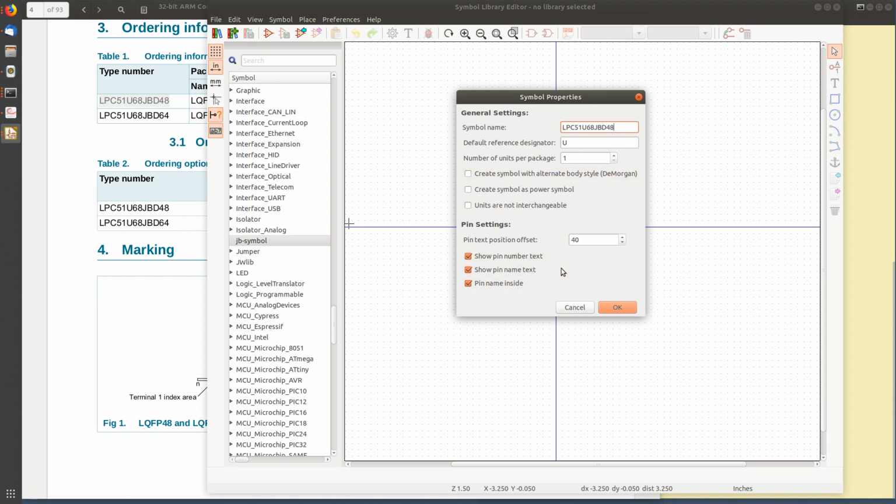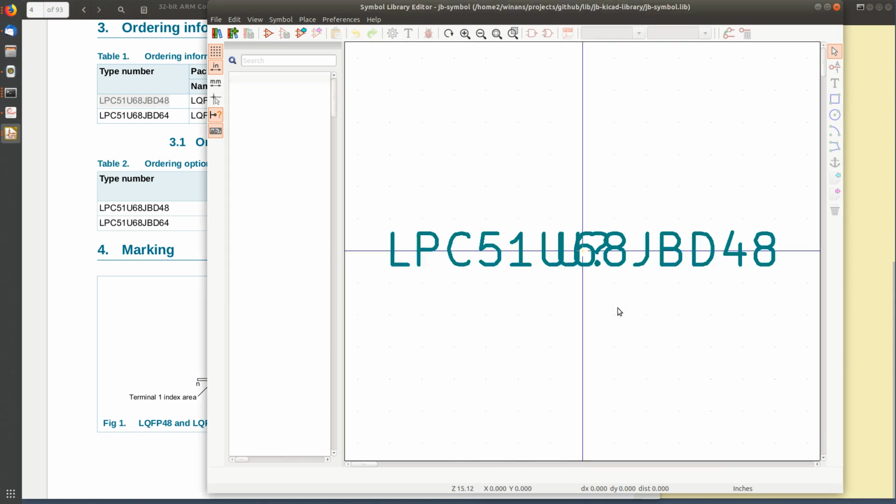These are more advanced features of complicated parts that have more than one subcomponent within them and things like that. Or am I going to create a symbol that really represents power? Do I want it to show up? Remember, there's a power symbol icon and a regular symbol icon in the schematic editor. Should it be in the other one, and so on? No, this is all generic stuff. It's an integrated circuit. So I'm going to hit OK.